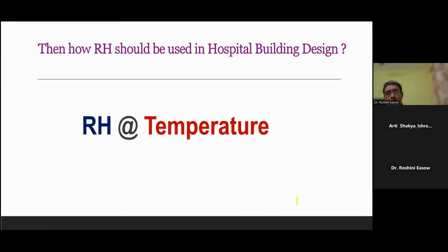It needs a lot of time to explain the RH and temperature relationship. But whenever we talk about RH, saying only the RH is not correct. It should come with a temperature. I know many medical appliance companies say that people are not doing the right thing to control the RH, like in Cath Labs and others, but they are also not correct. I tell them you have to state the RH and the temperature together. Then it will have meaning.